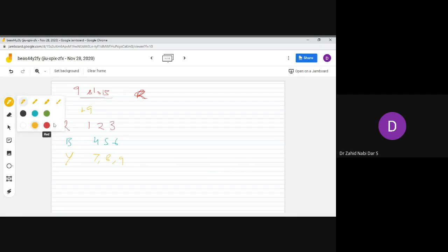Now when I'm going to the second coil, I have to add plus 9 to this, so it would become 10, 11, 12. Okay, similarly I have to add for blue also plus 9, so it would be 13, 14, 15. Again for the yellow also I have to add plus 9 because of the coil span, it's a full pitched. 16, 17, 18. So the total number of slots are 36.